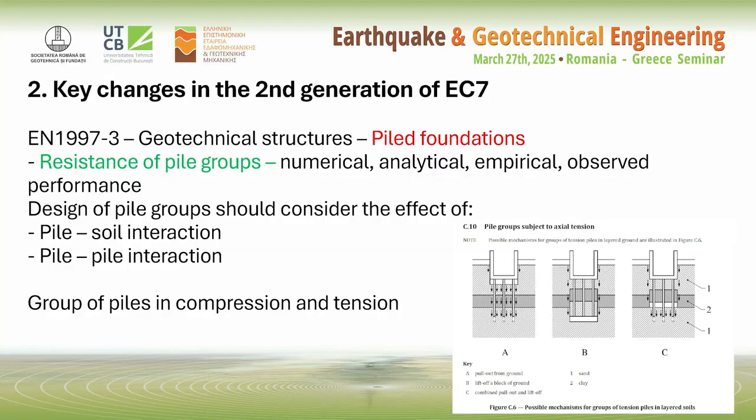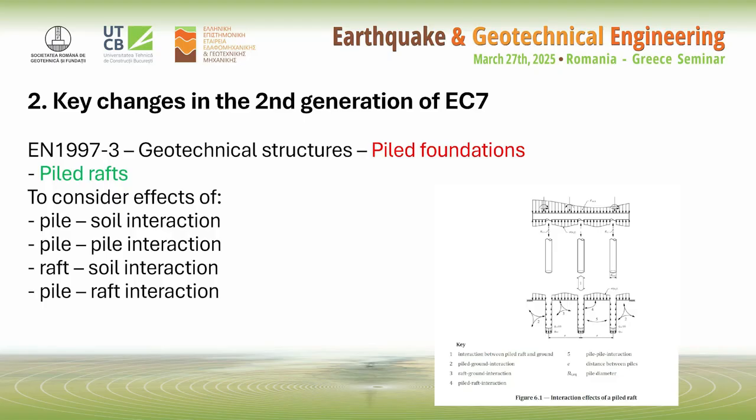As I mentioned before, now there is a subclause devoted to pile groups, and here we can apply either numerical, analytical, empirical, or observed performance for the analysis. And of course, we have to consider different types of interaction such as pile-soil and pile-pile. For piled rafts, there are also some considerations, and here we have to consider more types of interaction: pile-soil, pile-raft, raft-soil, and pile-raft interaction.